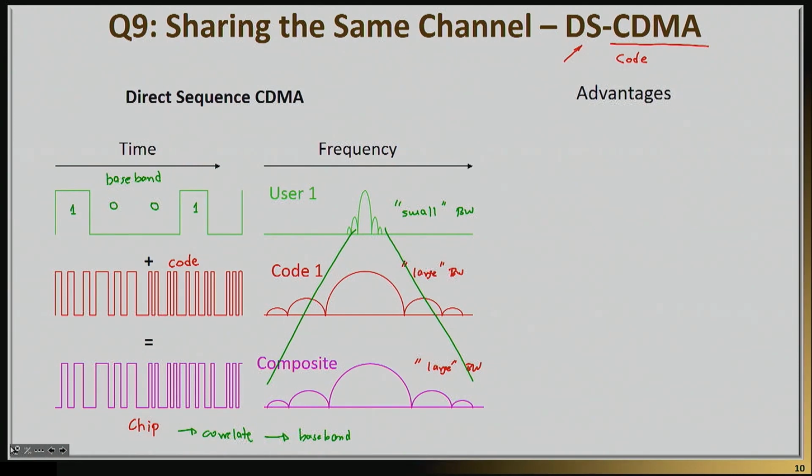One of the advantages is that it's pretty immune to interferers, people who are trying to intentionally corrupt you, so intentional interferers. Why is that? It's because somebody who is trying to eavesdrop here does not know your code. And to make things worse, these codes change continuously. For example, somebody could be changing this code 1,000 times per second. So, good luck finding this. In fact, it becomes practically impossible to crack that. Essentially, an eavesdropper only feels random noise. So immunity is a big advantage.